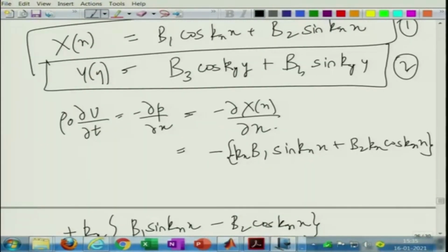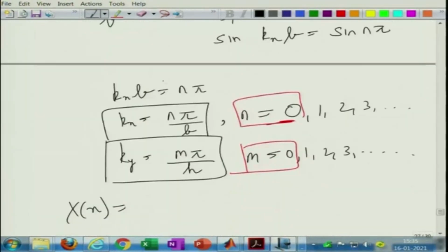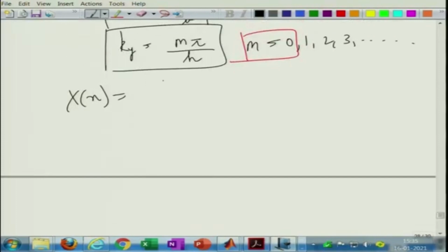So, eventually we are getting solutions in terms of cosines, not sines, for a rigid wall duct. That is, here we have a rigid wall condition, or normal velocity 0 along the perpendicular direction. Soft wall, in a hypothetical case, or in a lining, highly absorbent lining, that will set pressure to 0. So, we will get sines instead of cos. Wave numbers would be also different.